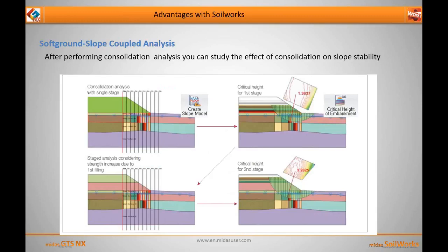The fourth advantage is that you can perform the soft ground slope coupled analysis. That is, after performing the consolidation analysis, you can study the effect of consolidation on slope stability after each stage. So it is very, very helpful to simulate the real ground situations.